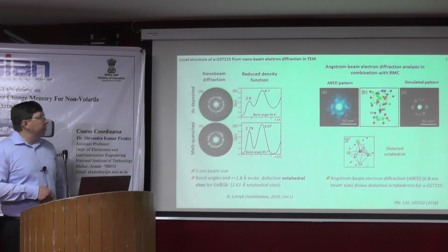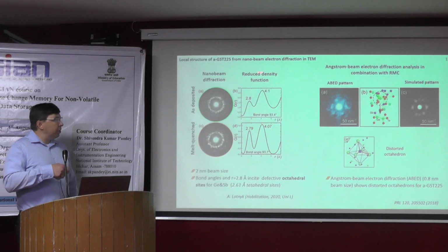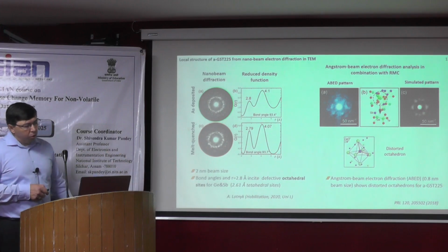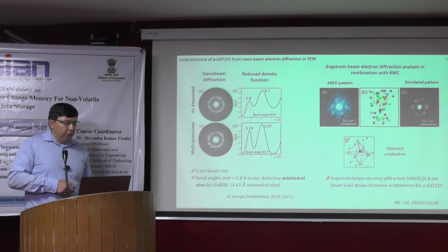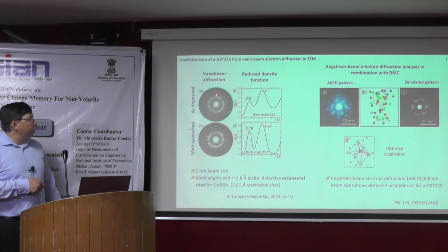You can also study the amorphous materials by using the RDF, as I introduced before. In the TEM, you collect nanobeam electron diffraction, and then you can calculate the reduced density function.